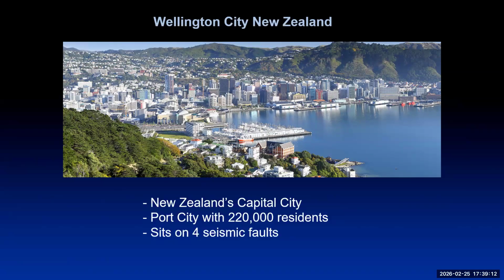And they did not understand why certain buildings got hurt and others didn't. Now, you could have two buildings that are exactly the same, and they could have different dynamic characteristics. And if the one with dynamic characteristics that align with the ground, it could displace tenfold more. And you will get that level of damage on top of it. So that's what happened. And they said, which one of these 10 buildings got damaged?